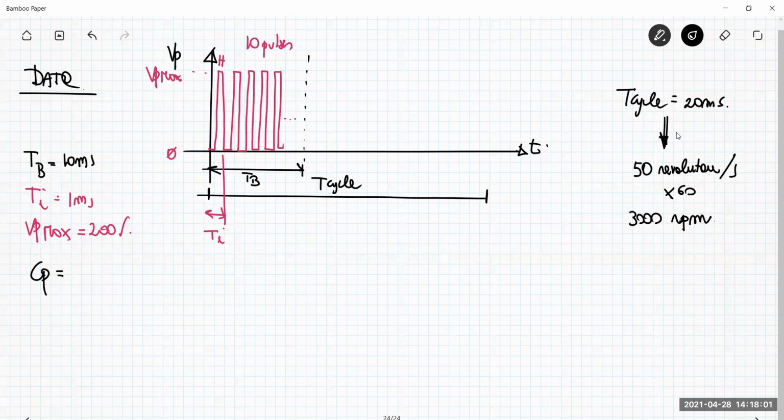CP, which is the model for my piezoelectric actuator, is 5 microfarad. It is the PZT material. Then I have some limitations. Remember, the limitation is that I cannot have acceleration very fast. So the maximum ratio of the voltage versus the time variation is 2 volt per microsecond.